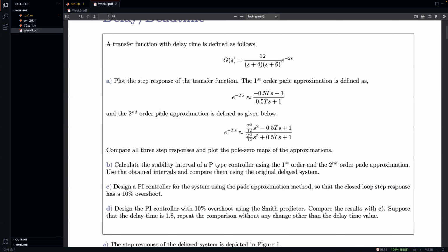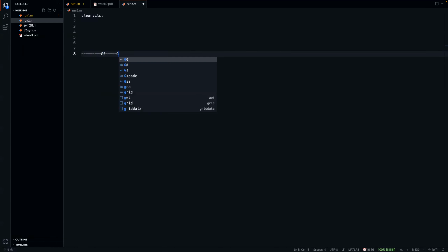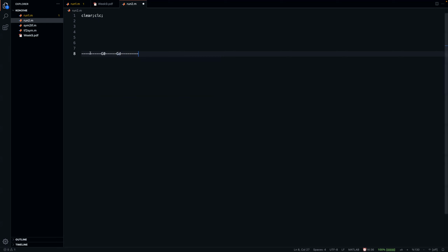Now, there's another method, which is called the Smith predictor, which is an alternative way of dealing with systems with delay. And the nice thing about this is that it uses a special structure in order to overcome the problems of systems with delay. So let me show you how it works. Now we have the non-delay part and the delay part here. And of course, we're designing a controller. And our special structure goes as follows.